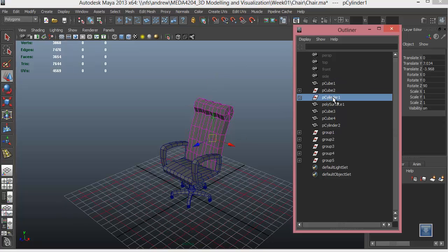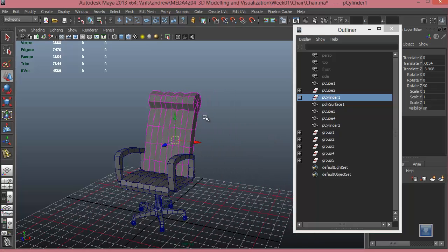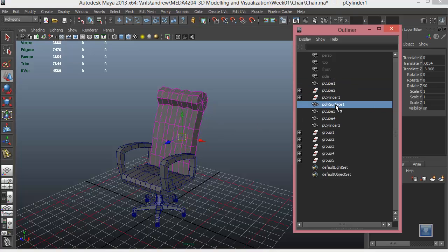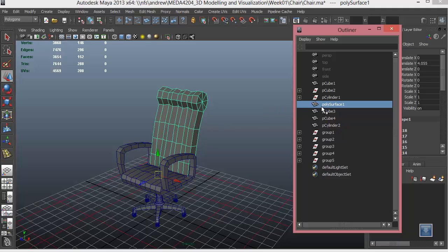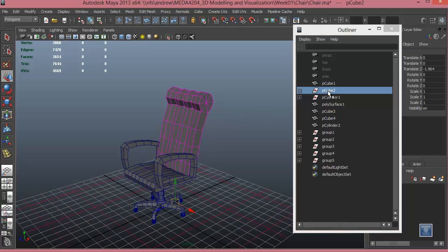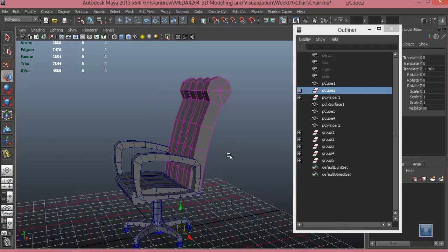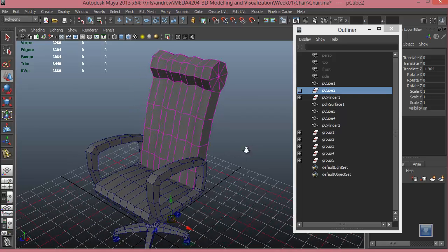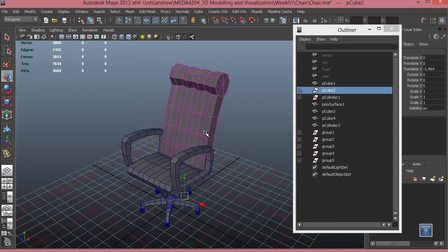And we have two other objects which do not show any complete object, but show some pink color on this one mesh. And if I click on the next one, it shows that this is the mesh. Now why is it showing the pink color? Because it says that this particular node is connected to this object. Now if you remember, we made two meshes, one cube and one cylinder, and we combined them into one final object. So what happens is, in Maya, every mesh that we create will have two nodes attached to it. One is a transform node and the other one is a shape node.